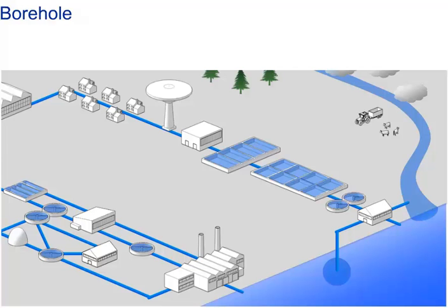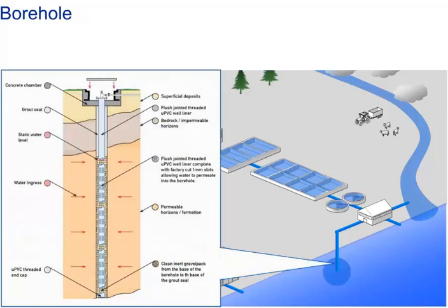Besides surface water, many of our customers prefer using boreholes or wells as a source of supply of water. There is one distinct advantage: natural filtration through the ground allows for a much cleaner product to be brought into the treatment plant, thus reducing the amount of chemicals used as well as energy to properly clean the water.